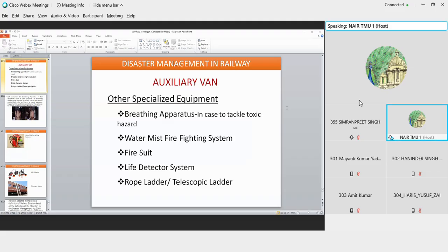The derailment may happen also due to cracks or faults in the tracks. You will find that we face scenarios where rail fracture happens. A rail fracture may happen because of temperature variations. A rail fracture may also happen if a flat wheel or a skidded wheel has gone on top of the rail head and it gives an impact and breaks the rail into pieces.